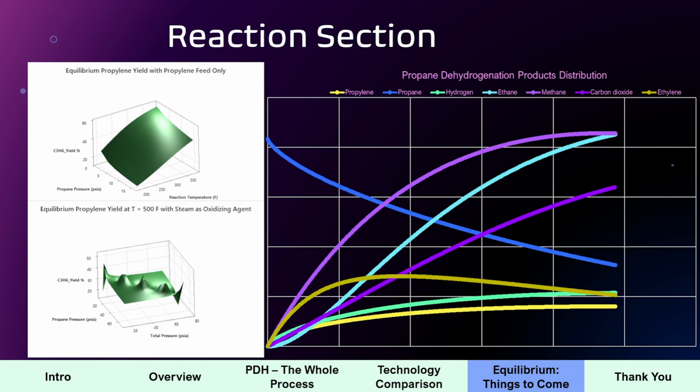And it actually gets worse when we're talking about temperature as well. One of the biggest aspects in terms of equilibrium in this kind of reaction is that the simplistic view of a single reaction pushed everyone to focus on 600 plus C. Because the thermodynamics of the first graph, the top graph, is telling you that if I want high selectivity or high yield of propylene, I need to push my temperature in that direction.